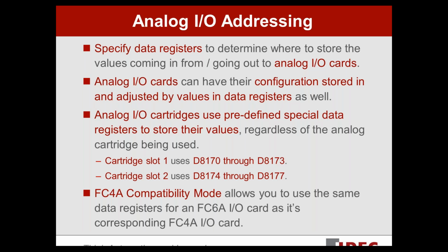The analog I/O cartridges use predefined special data registers. And if you guys remember, special data registers and special internal relays are areas in the PLC that just automatically exist. We've created them, we've defined their functionality in the firmware. You don't have to do anything to get them to work. They just do, okay?